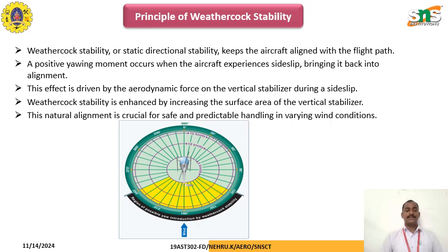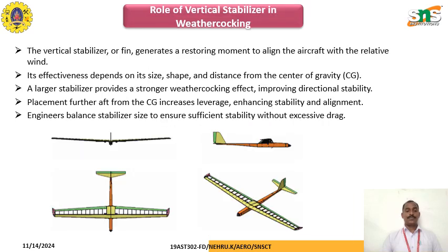This effect is driven by the aerodynamic force on the vertical stabilizer during a sideslip. Weathercock stability is enhanced by increasing the surface area of the vertical stabilizer. This natural alignment is crucial for safe and predictable handling in varying wind conditions.